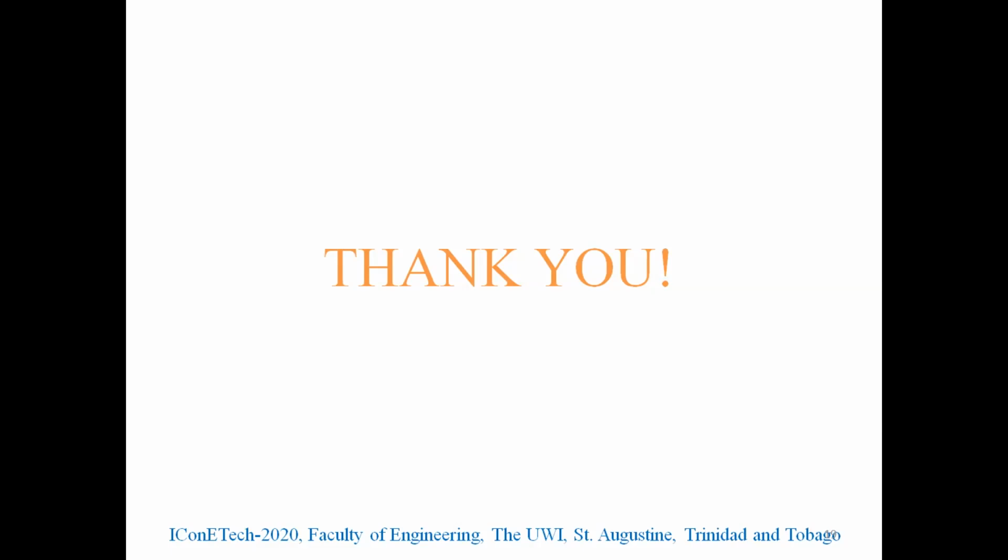And large eccentricities. Large eccentricity also affects the maximum pressure, but we didn't get time to put in all of those graphs because the slides were limited. But I did consider where the eccentricity ratio was increased, and by increasing it, we have the maximum pressure increasing. That is very good, because if we want a large load carrying capacity, we could do that. But remember, not every situation will want it to be carrying a large load, it might be a small load, depending on its application. Okay, thank you.